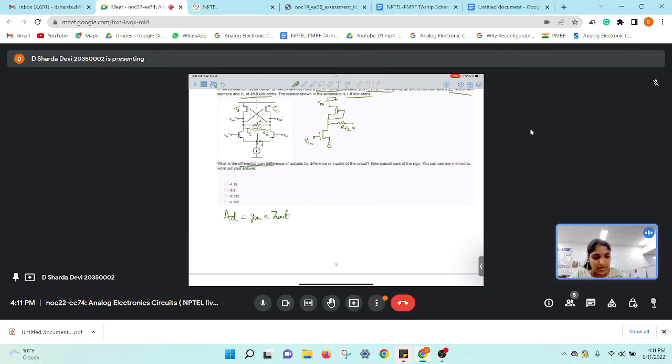Now, this is our V out. This is the input, so input gm will come from this gmN, which has already been given. The only thing we need to find out is Z out. So how much is the value of Z out? Looking at this, three resistors will be in parallel, looking up, looking down, and R by 2.